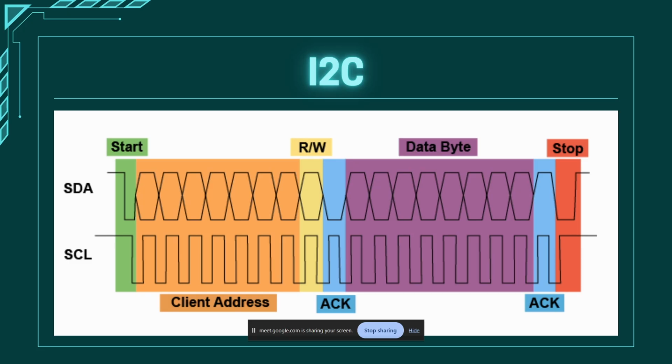The clock ensures that the data is not undergoing a transmission while we read it. The clock signal makes sure that the data is read when the data is stable, rather than while it is undergoing a transition. As you can see, the data can move through intermediate values.